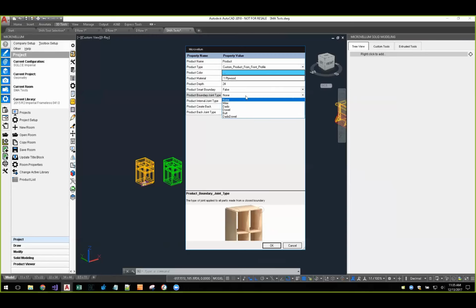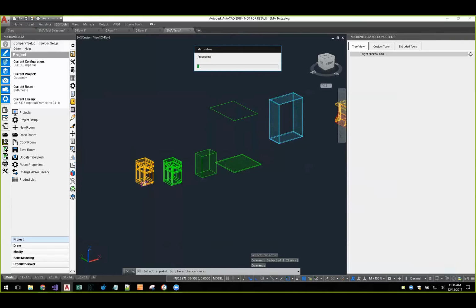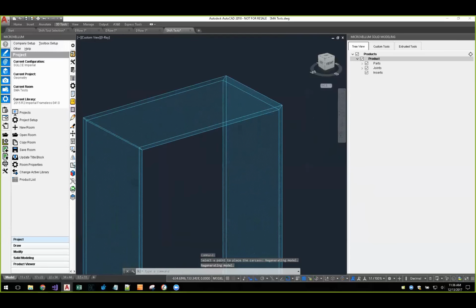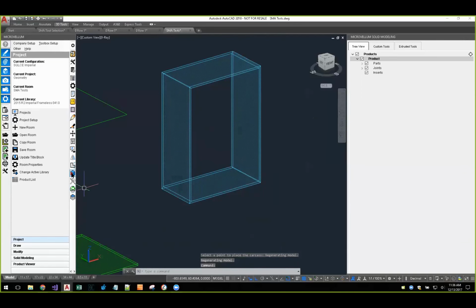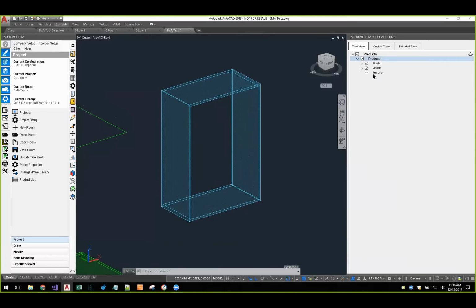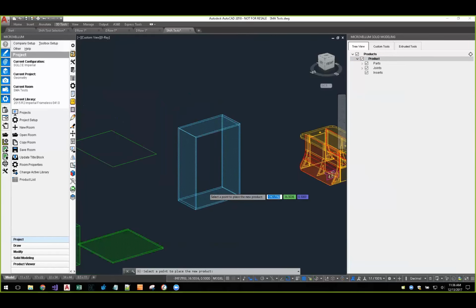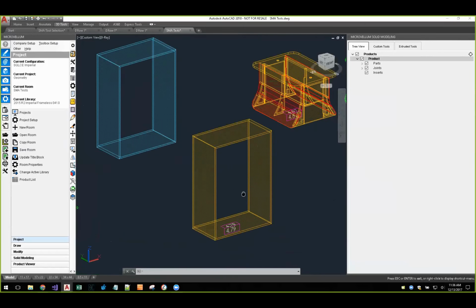Let's see, I think we'll want to do miters here. What that does is actually build a box for me out of those 2D lines. It's got machining on it, like the miters. There are two ways I could deal with this. I could use that one-off solid model analyzer button to bring that into Microvellum as a spreadsheet-based product. Or here, I could save it as such, which just invokes the same algorithm, and it becomes a product there.